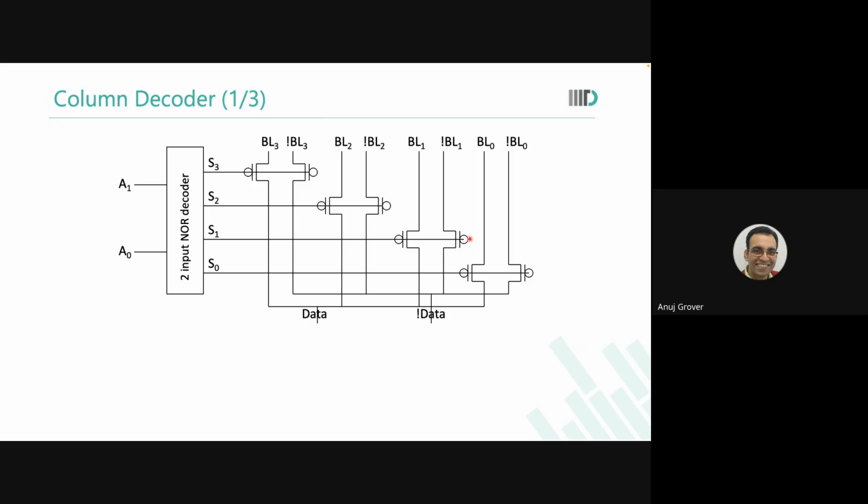How is it acting as DeMUX? Whatever is on data, it can go to BL now. Depending on which of these two is selected, data can also go up there to the bit line. A pass transistor is equivalent on both sides, right? So it transfers bitline to the data pin, and also data pin to the bitline. Both sides it will do.